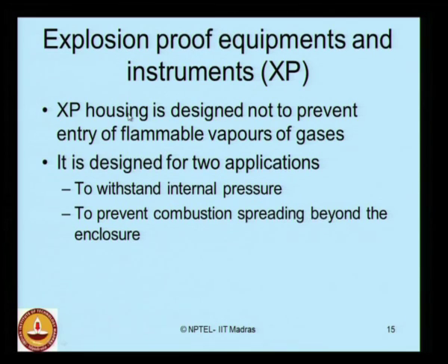In such cases, we are not protecting the enclosure from the entry of flammable gases. We are actually making the enclosure withstand internal pressure and prevent the combustion from spreading beyond the enclosure. That is what we call explosion proof design.